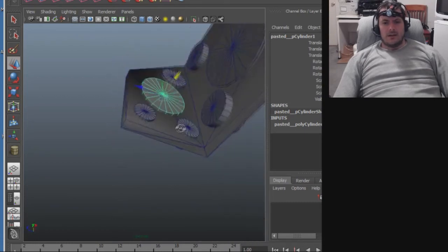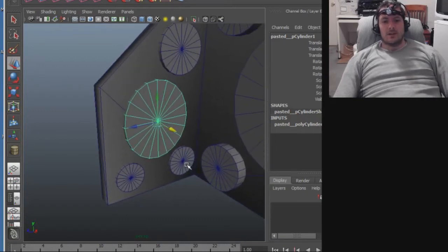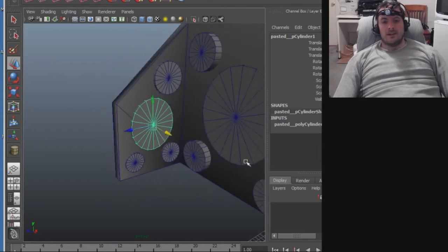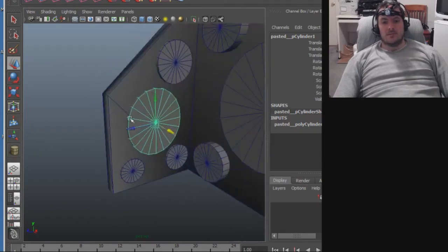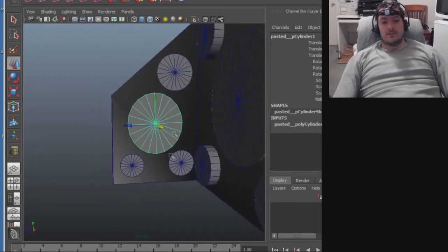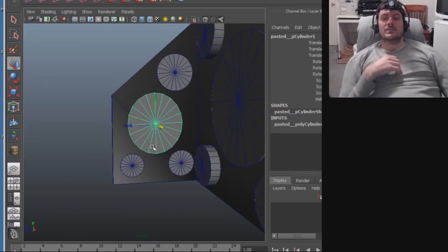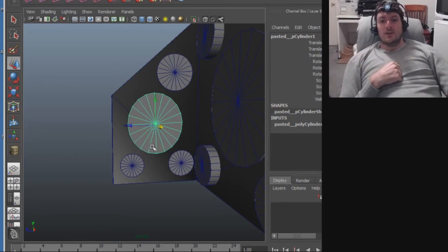Now, I want to save these circles and 3D print them separate as plugs, and we can glue them into the holes. But because I'm running way behind on my 3D print, those plugs would take forever to print as well, days. So what I'm going to do is just put some masking tape over the hole on the back side and pour ABS slurry sludge into it, almost like pouring cement into a plastic bucket. And that will cure, creating a solid fill of ABS plastic.